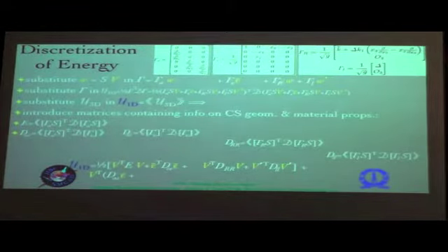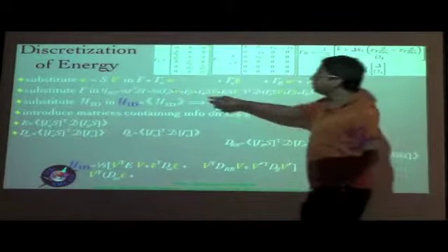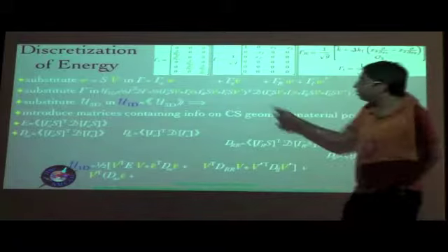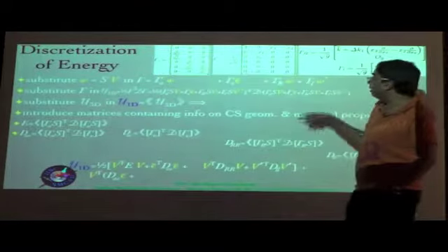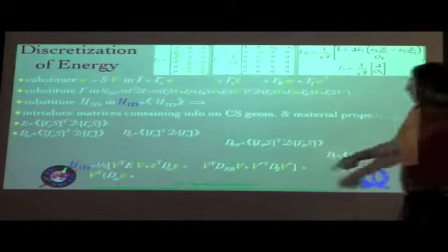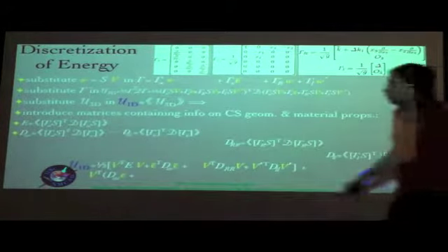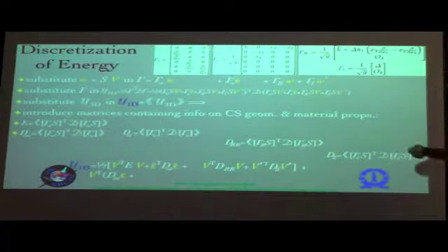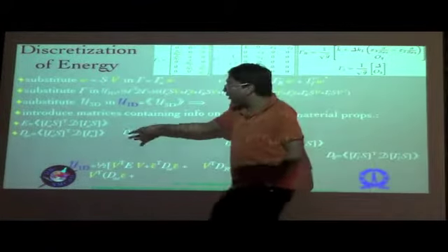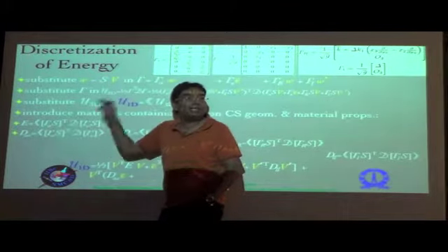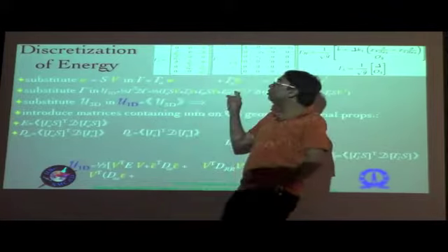So next we go to the coupling terms. We take the first term on the left hand side and the second term on the right hand side. So you have a V transpose coming from that and basically an epsilon bar coming from that. So you have a dA epsilon associated with that, whose expression you see over here. In most cases you would have the operator operating upon the shape function, but that's only if the warping terms were involved with it.